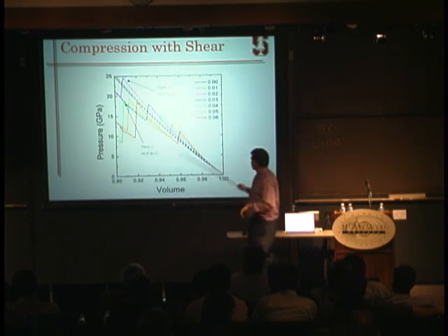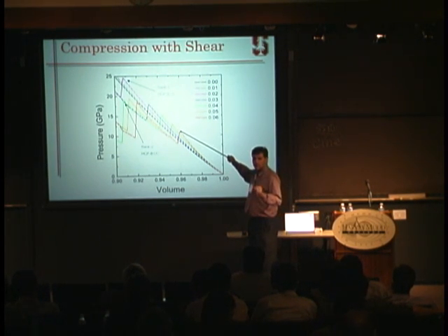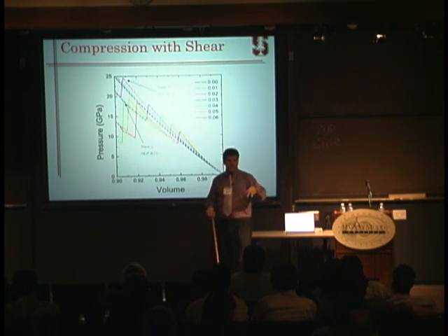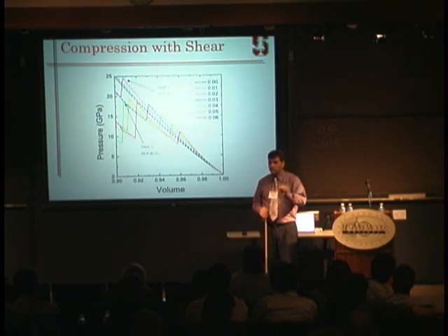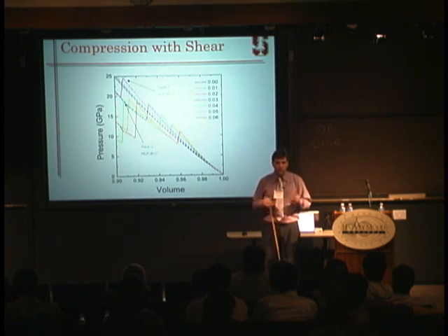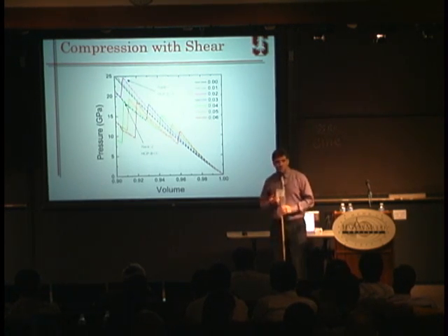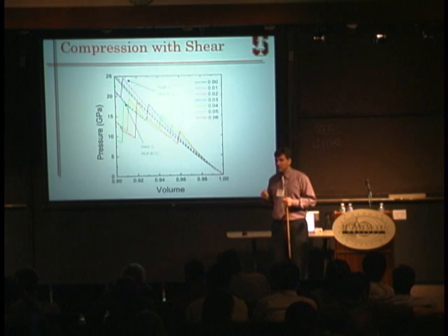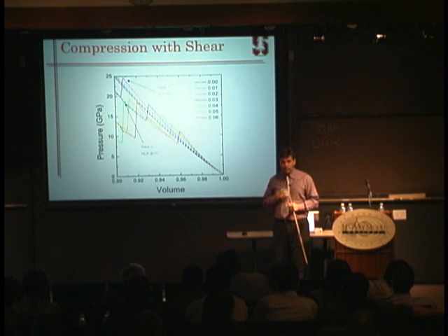You keep on increasing, you get to 0.06. This is the red curve, and you transform at 13 gigapascals, okay? You keep on going, you transform again, a rank 2 laminate, okay? But you see that with very little distortion, you change the value of the onset pressure tremendously. And that's the explanation for the spreading of measurements that people have. And one thing to notice here is that we did not use an experiment to compute that the transition pressures were 13 gigapascals, which is what people measure. So we did this entirely with the computer.